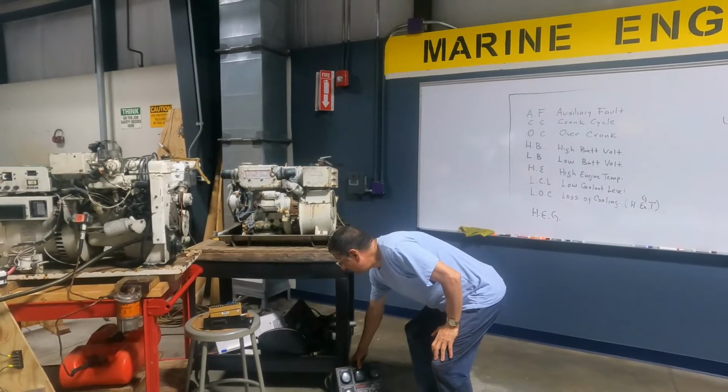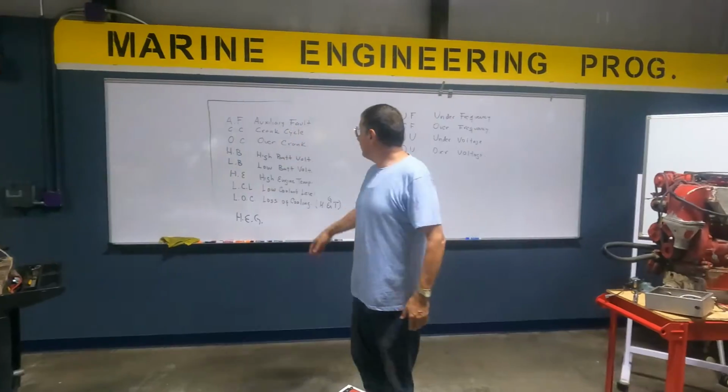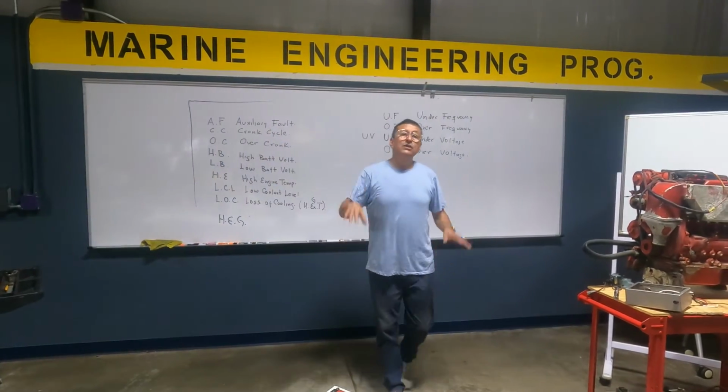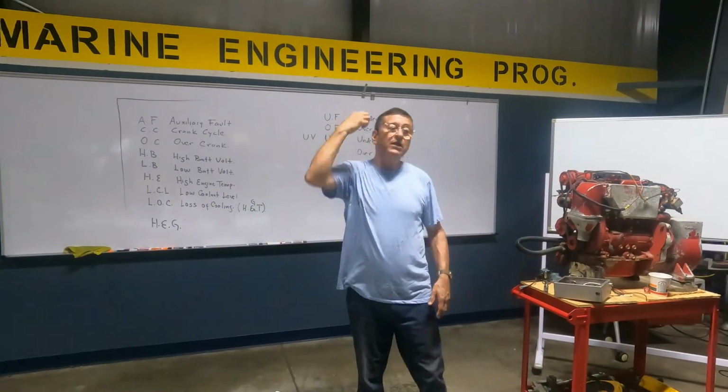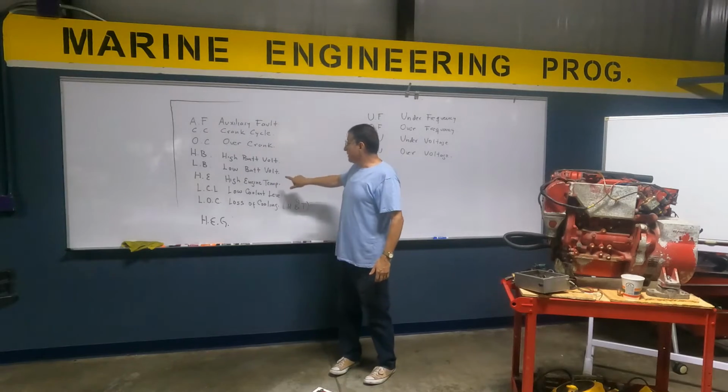And the recommendation is, some manufacturers ask, can I use the generator? No, my friend, no. If that code is activated, you need to solve the mechanical problem in the engine, and after that try to use the generator. Okay, this is related with temperature on the engine.